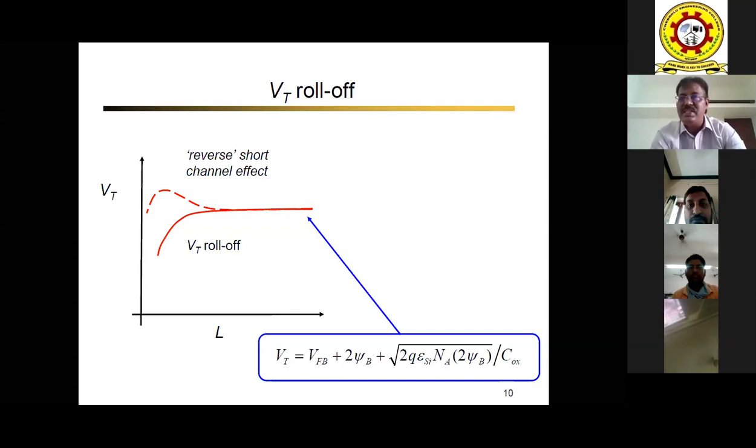So this voltage opposes your conventional gate voltage. Thereby, to turn on the inversion layer, your gate level voltage should be higher. So that is what reverse short channel effect is. So when people are going for one kind of research, unnecessarily they come up with unknown side effects. So reverse short channel effect is one of the side effects of halo doping technologies.